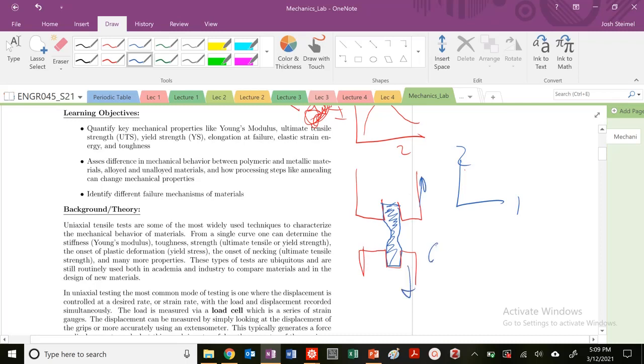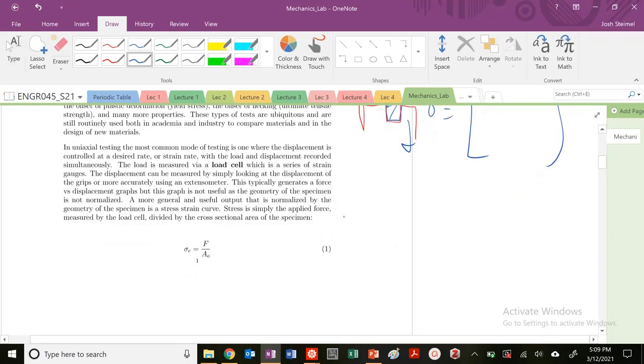So in our stress tensor, it is the simplest case, the only time when you could really use Young's modulus instead of my other most favorite, the equation that we all know and love so much: epsilon ij is equal to 1 over E times (1 plus nu) sigma ij minus nu sigma kk delta ij.